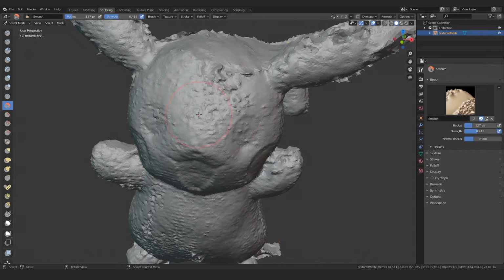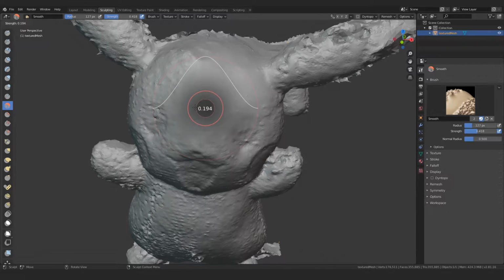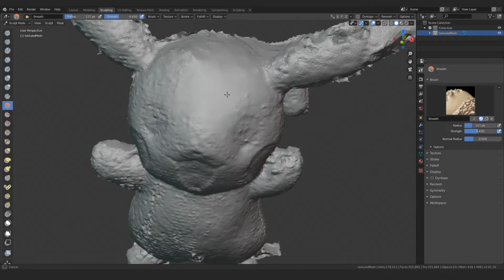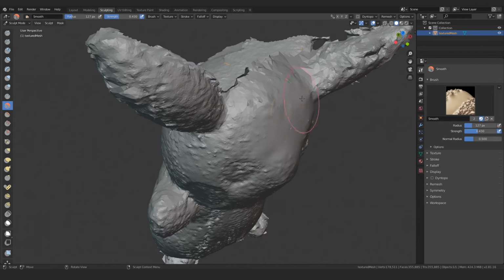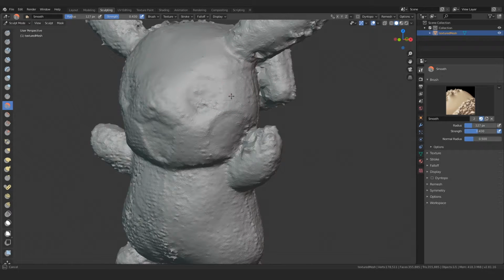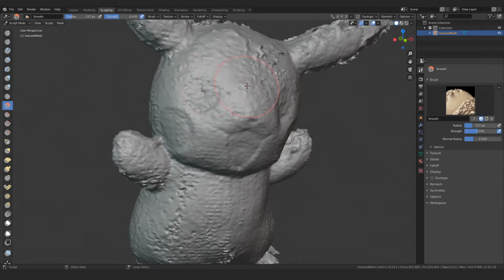By default it's 0.7. Here now it's a little bit less, and then I can change it all the way down, and now you can see it's not smoothing as much. So I like it to be closer to maybe around 0.3 or 0.4. That seems to be pretty good, because we're not looking to really change the silhouette. We just want to get rid of some of this extra bumpy jagged detail here. And so I'm actually going to undo some of this.